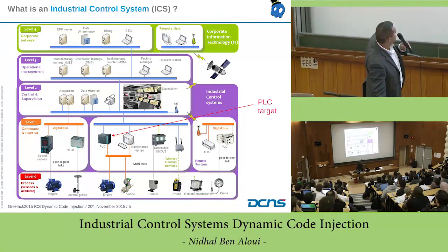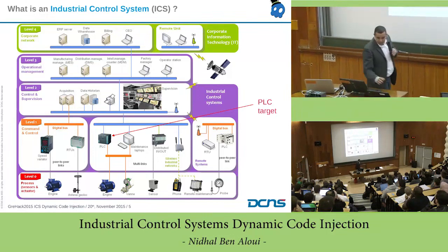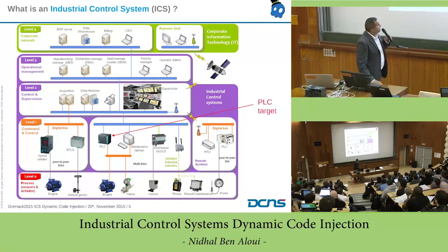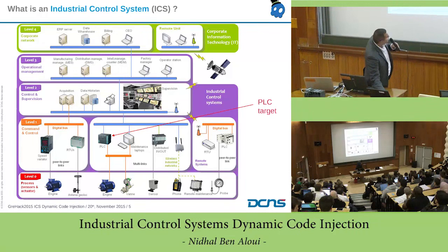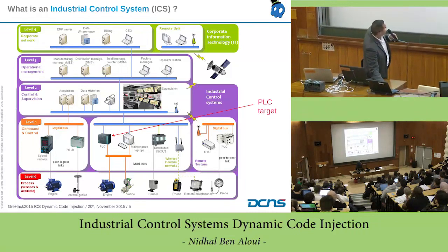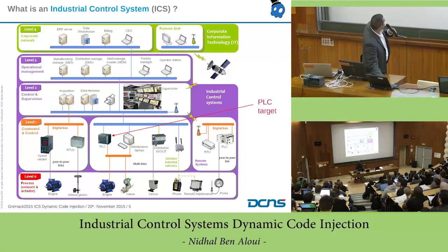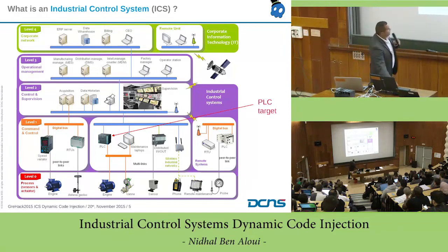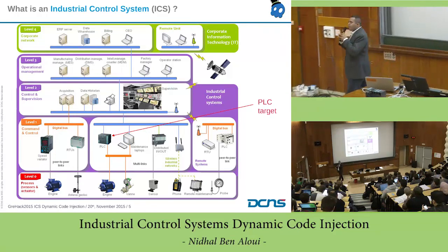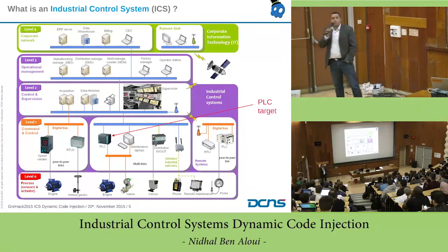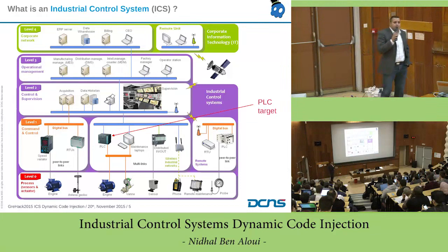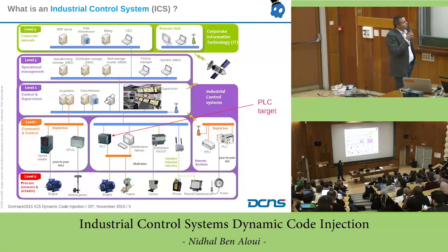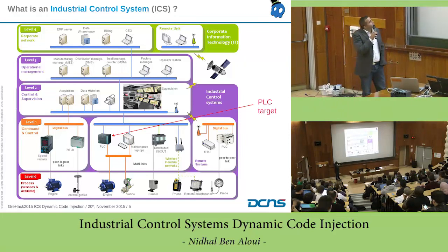Here we have some PLC, maintenance laptop, our development station like this. This is a real station from Siemens to develop some code on this PLC. You have sometimes a distant equipment or a Wi-Fi hotspot, digital input, output, wireless, speed variator, something like that. So you use a bus here with a specific protocol like Profinet, Modbus, or Profibus. Sometimes it is a specific protocol, and sometimes a normalized protocol, to communicate between the PLC and the actuator or the sensor.